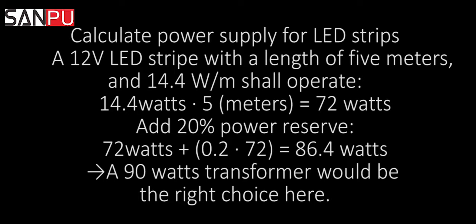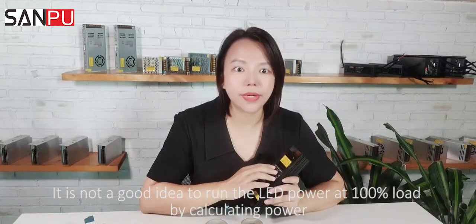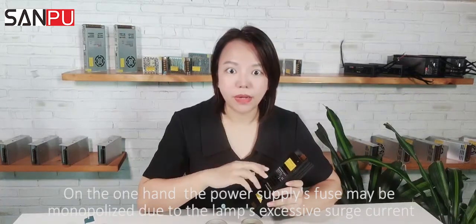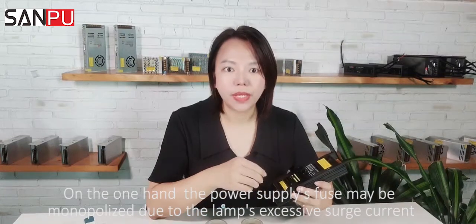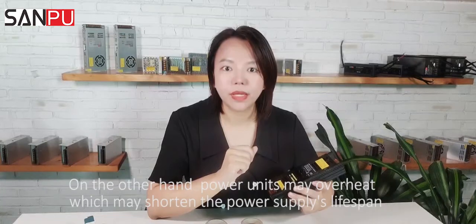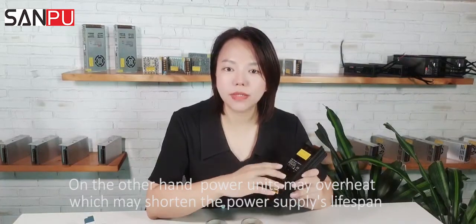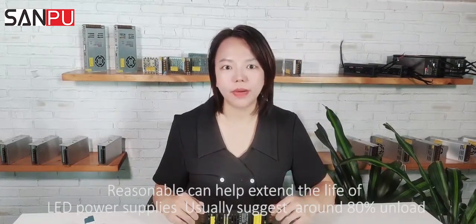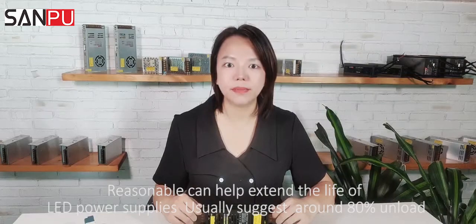Add 20% power reserve: 72 watts plus 0.2 times 72 equals 86.4 watts. A 90 watts transformer would be the right choice here. It's not a good idea to run the LED power supply at 100% load. On the one hand, the power supply fuse may blow due to the LED lamps' excessive surge current. On the other hand, the power unit may overheat, which may shorten the power supply's life. A reasonable reserve can help extend the life of the LED power supply; usually we suggest around 80% load or lower.